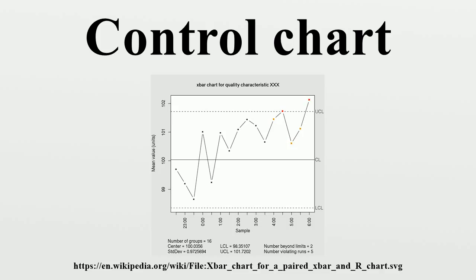The chart may have other optional features, including upper and lower warning or control limits, drawn as separate lines, typically 2 standard errors above and below the center line. Division into zones, with the addition of rules governing frequencies of observations in each zone. Annotation with events of interest, as determined by the quality engineer in charge of the process's quality.